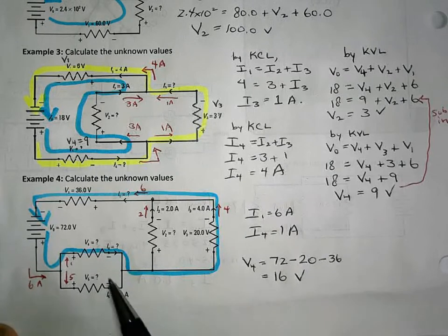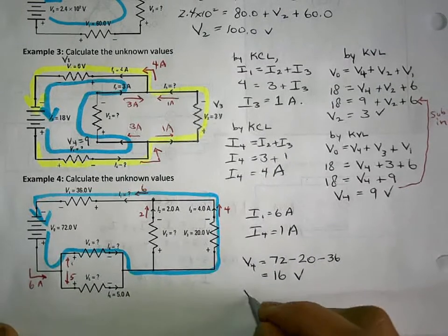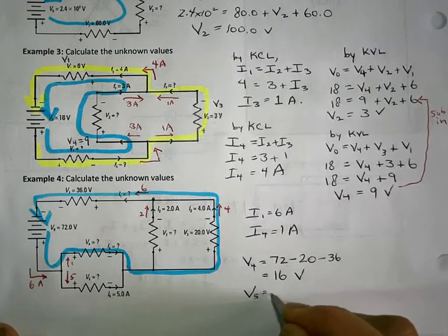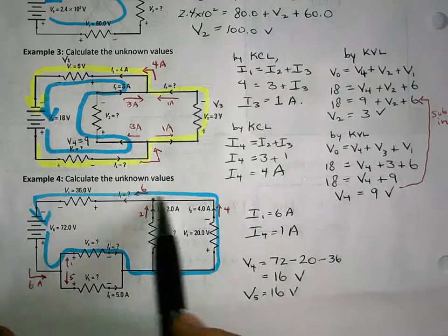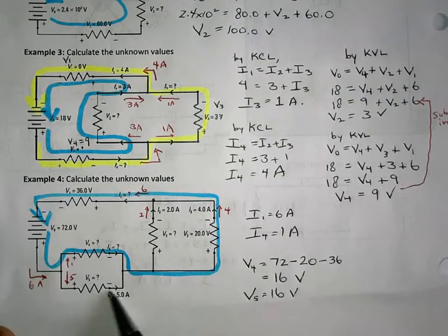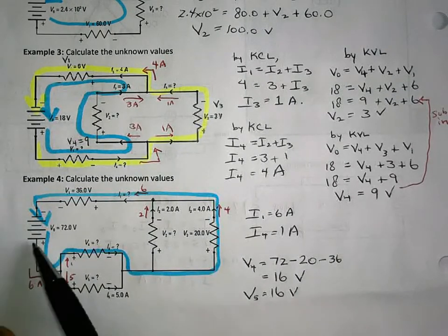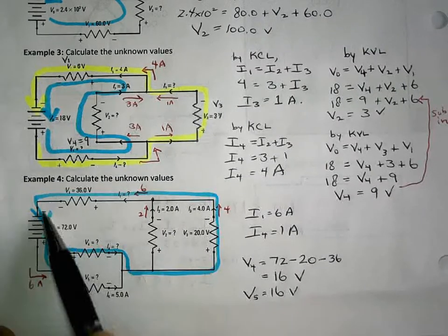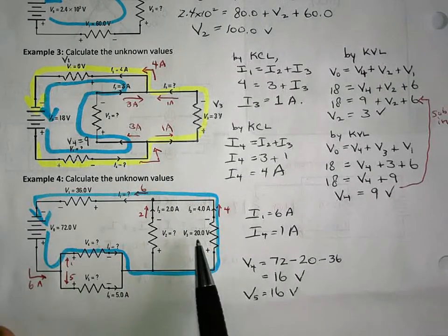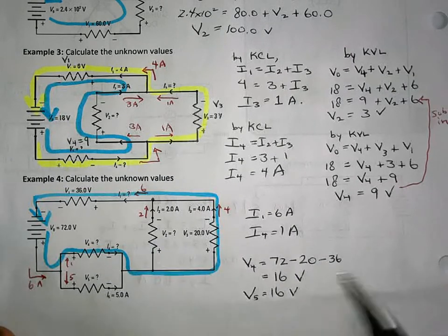Now, the rest we could figure out pretty quickly. Because these are parallel and there's only one resistor, then we know that V5 has to be the same, 16 volts. If you wanted, you could draw another loop and figure it out. So there's a path that would go like this. Then there's another path where you go through either of these, and then you go through V2. Again, it's no surprise, V2 is parallel to V3, so this has to be 20 volts.